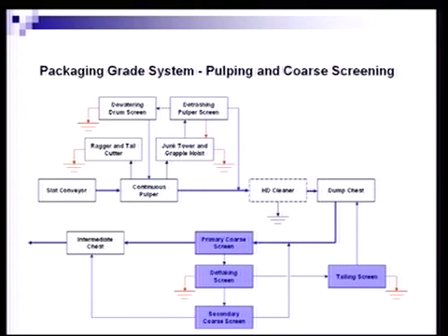There's a primary coarse screen whose function is to remove the flakes and the debris, concentrate that debris so that the deflaking screen, which is in the secondary position, has some material to work with. And in that position, we'll want to add some additional horsepower into the screen. We'll want to have a different type of screen so that we can do some fiber recovery by treating the flakes in particular.